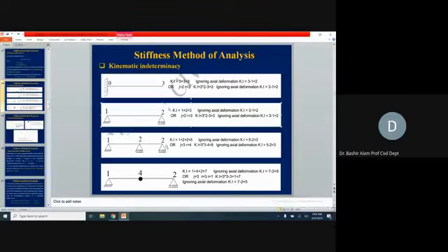And at the right support, also we have a rotation as well as a translation. So here now you can see the summation. Those unknown joint displacements are written at the top of these joints: 1 from here, 2 from middle, and 2 from the right support. So 1 plus 2 plus 2 is equal to 5 degrees. This is the total kinematic indeterminacy of the problem.